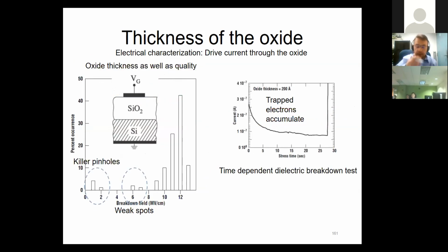All right. So there are other ways to characterize the silicon dioxide. We just looked into the non-destructive optical way, but there's of course an electrical way too. In that case, you have to create the same configuration that we worked on before. You need to have a metal, an electrode. It could be polycrystalline silicon too, but underneath that you can put your oxide, the thermally grown oxide, and we have the semiconductor. Again, it's the same MOS structure, metal oxide semiconductor structure.